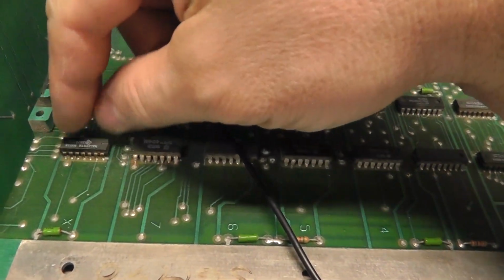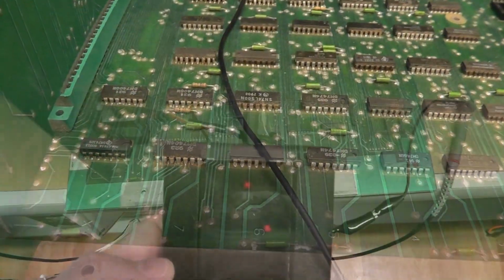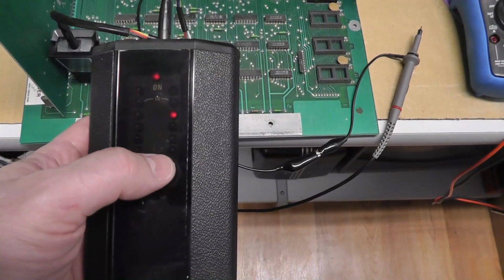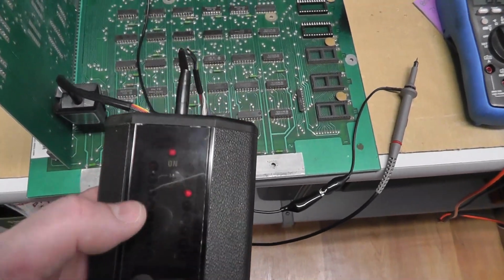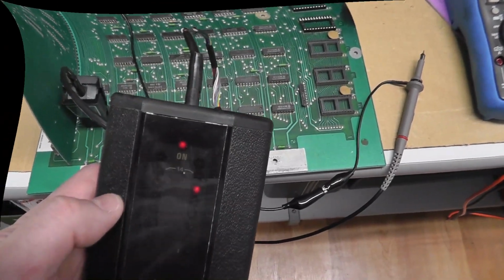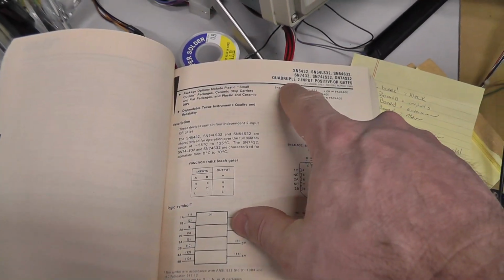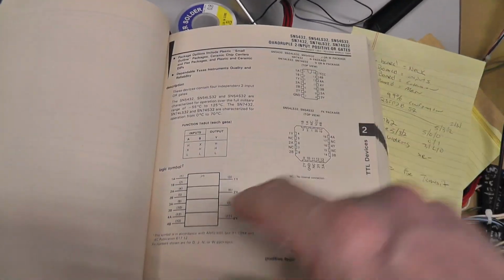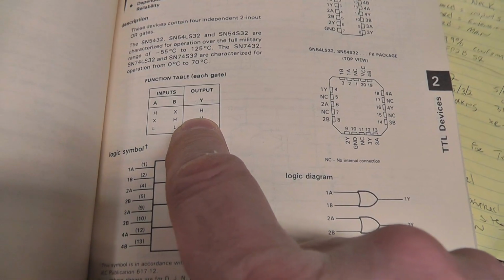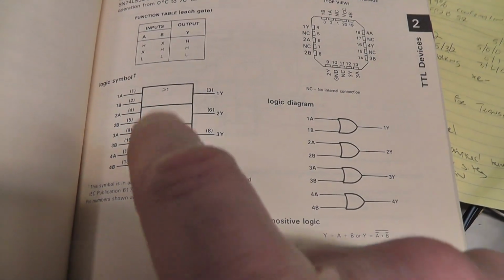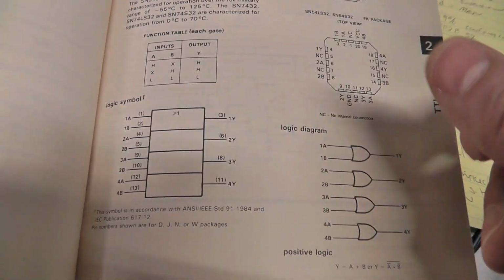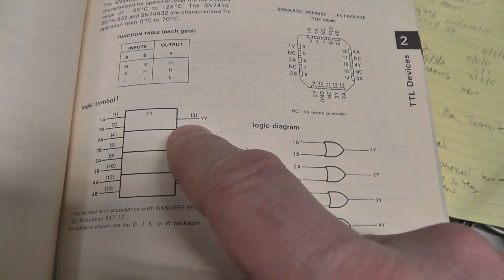So I'm going to see if my comparator shows it bad. Alright, I have my little logic comparator. It says pin 6 is bad. 1, 2, 3, 4, 5, 6. Pin 6, the output there. I'm going to look up what a 7432 is. I don't know off the top of my head. Yeah, 7432, it's a quad, 2 input, positive OR gate. So if either A or B is high, the output should be high. And it's interesting that pin 6 is showing as bad when I suspected, based off of just looking at the scope, pin 3 would be bad.